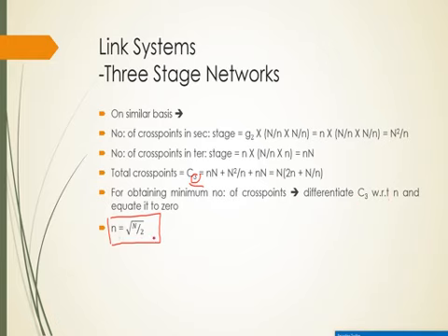Now next we have to check the other condition, that is, m greater than n or m less than n. Let us consider m greater than n, that is, the number of incoming trunks greater than the number of outgoing trunks. So in that case, let m be the number of inlets for each of the primary switch, n be the number of outlets for each of the tertiary switch. Sorry, I wrote secondary; it should be a tertiary switch. It's a typo.